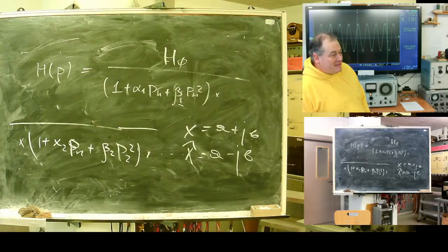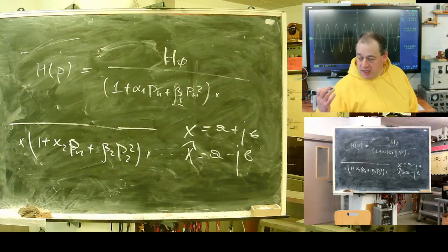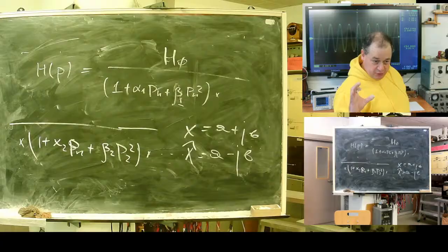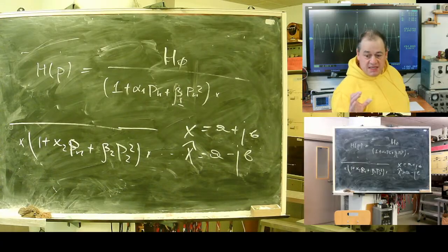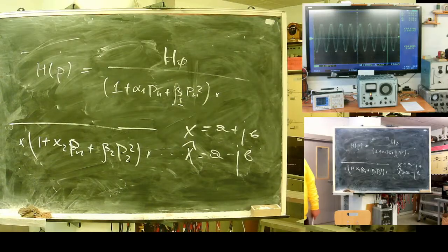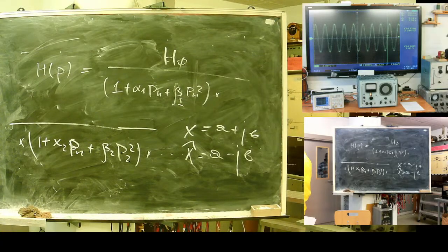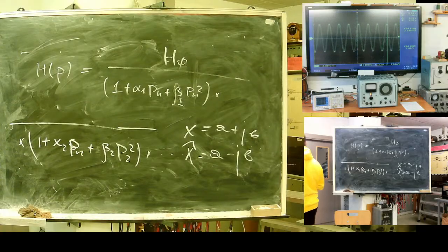Such a filter cannot be passive, but with the addition of an amplifier it works, especially when your input transducer is a transformer, which can be loaded. There is no problem of energy consumption in this preprocessing part. If you deal with something with low load capability, like a Rogowski coil or small size air gap transformers, you don't have load capability. This means you cannot use signal energy in the filter, so you will need an active one.